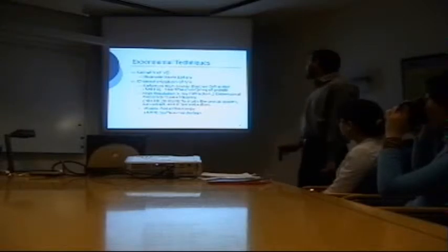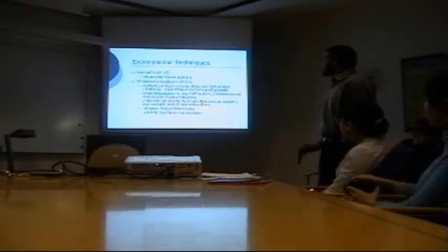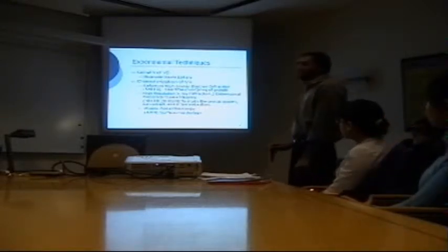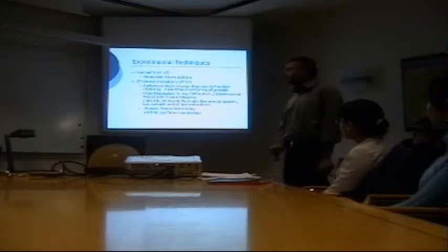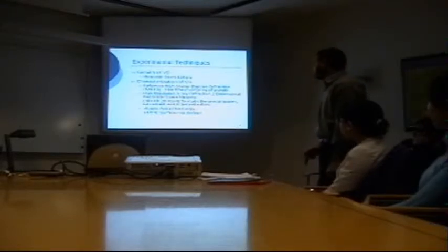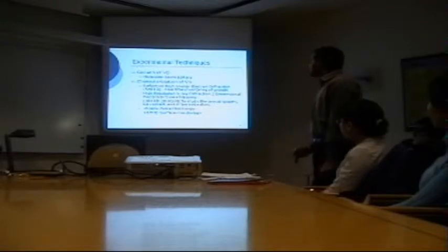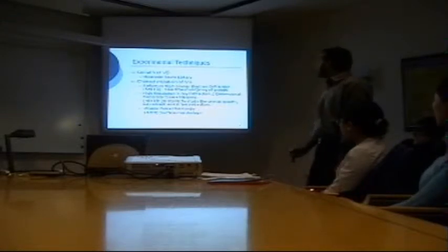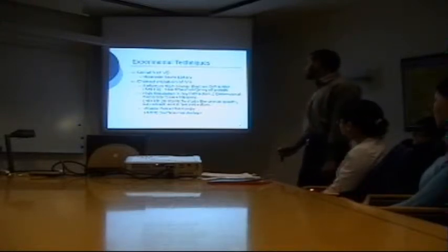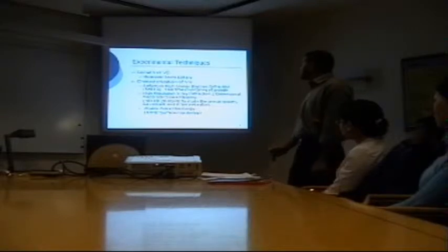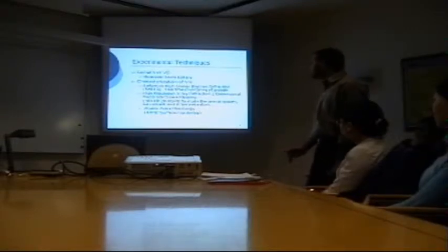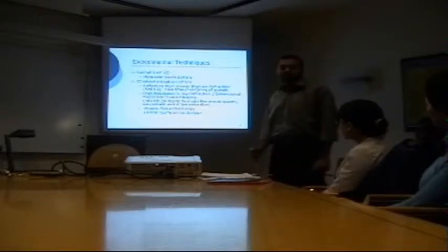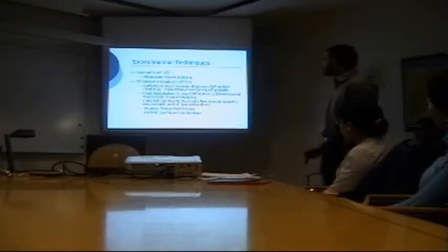During this project work, to grow these virtual substrates, we use the molecular beam epitaxy technique, and for characterization purposes, we used reflection high energy electron diffraction for the real-time monitoring of growth, and high resolution XRD 2D reciprocal space mapping to study the crystal quality and to calculate the germanium content and the strain relaxation. To study the surface morphology, atomic force microscopy was used.